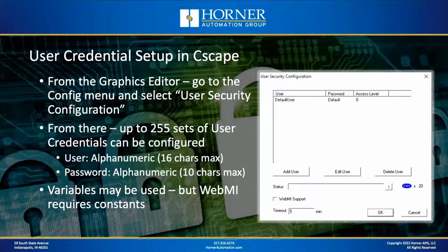Generally, I would recommend that for each of these sets of user credentials that you want to enter in, you go ahead and just hard code those in. You could assign variables to those, which makes a lot of sense, except WebMI requires constants to be entered in. You don't have the ability to use variables for your user credentials if you're using WebMI. And WebMI is a pretty valuable feature. And keep in mind, you can enter up to 255 sets of credentials. So you can have a whole bunch of credentials for operators that have the same access level, but you can hand out, or your end user can hand out, unique user credentials to each of those guys so they're not sharing each other's credentials, for instance.